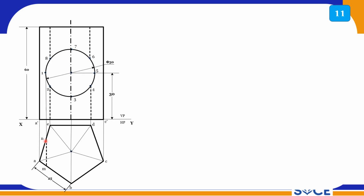So I am marking 2 points here to measure the true length. That is the purpose of these 2 points M and N, and for the remaining points there are no issues. So you have 2 here. Similarly for 5 I am getting these 2 points S and R. These are the reference points to measure true length from the top view, so R, S and also M and N.